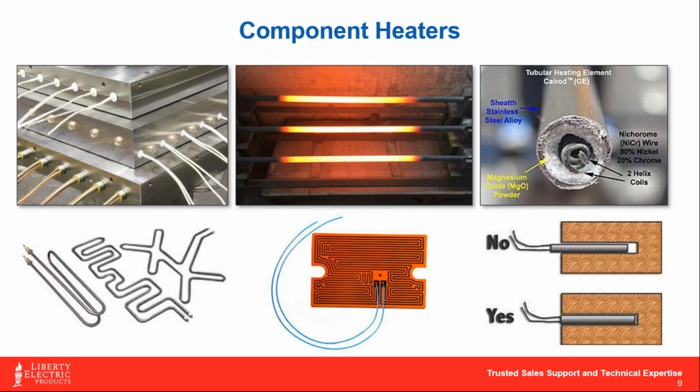What I do think is a pretty interesting factoid is many times those resistance wires are as thin as 37 gauge, which, to put that in perspective, is about a third of the diameter of dental floss. So it's really thin stuff, and you can hit it with 480 volt, even 600 volt, and it holds up for years. I've always been pretty impressed by that. Bottom left-hand corner, the next time you walk through a Lowe's, Home Depot, or an appliance store, open up an electric range oven; that's a great example of a multiple bend tubular heater on the bottom of an electric oven. So we'll see these things in all kinds of different shapes, configurations, and outputs.